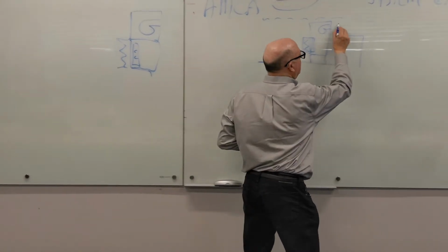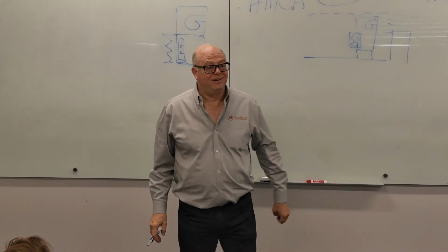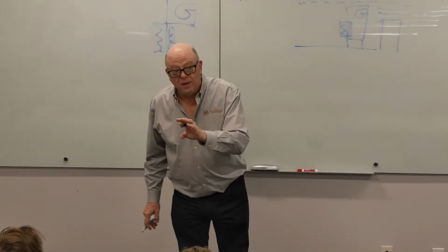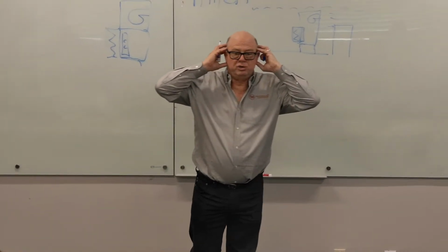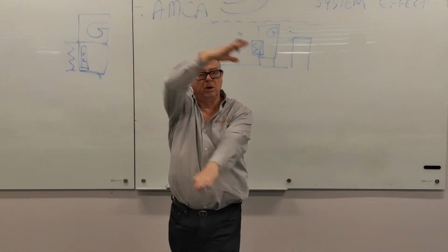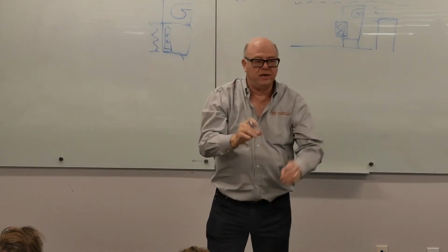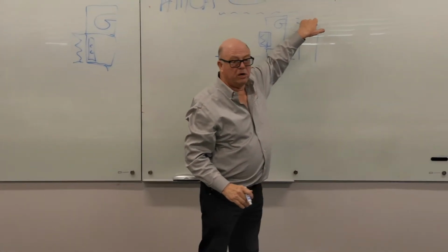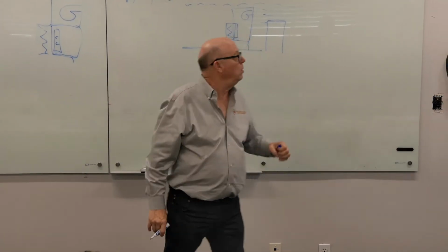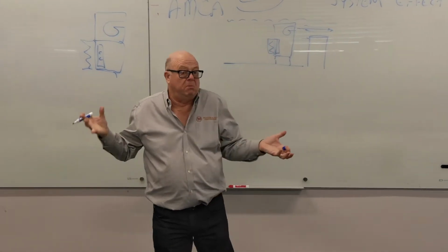And then he'd run the duct across overhead. And honest to God, sometimes he would actually get 10 duct diameters. And then what you did as sound insurance is you would have 2 layers of 5/8 inch chipboard crossways. Because when you do that, that is a pretty effective duct rumble inhibitor. And so you would have a pretty straight shot there, so you'd minimize the duct rumble as much as